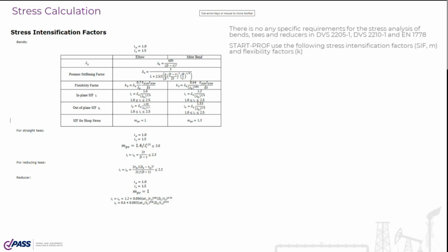So it will be allowed to enter any custom values of stress intensification factors and flexibility factors in the current official version. The stress intensification factors and K factors are calculated automatically using the following equations.